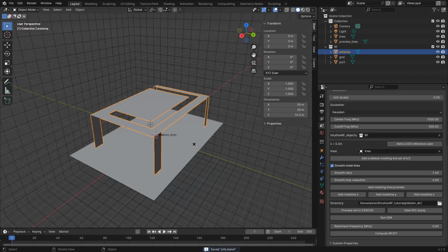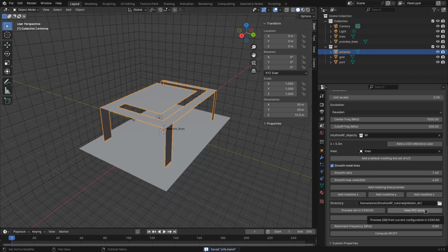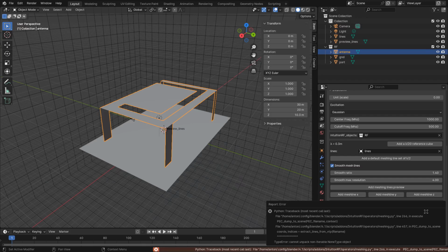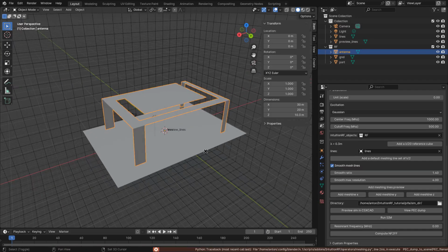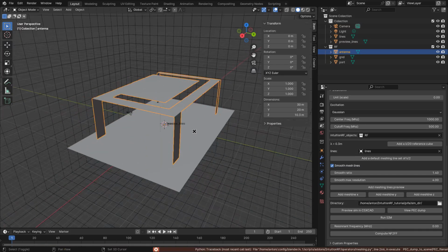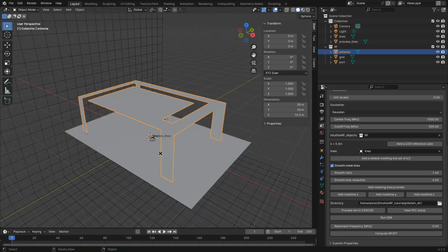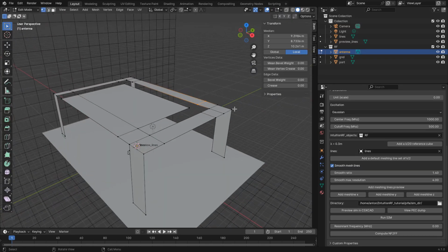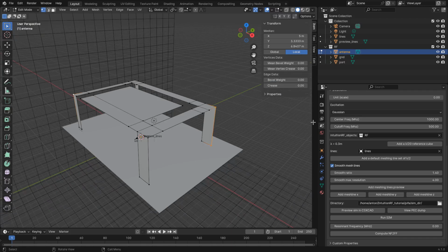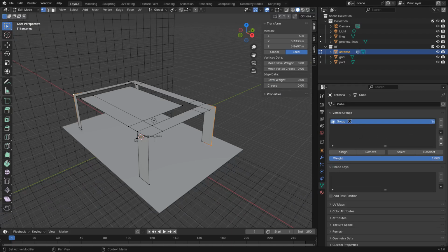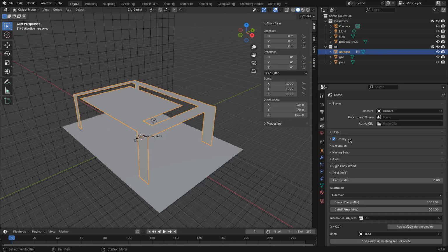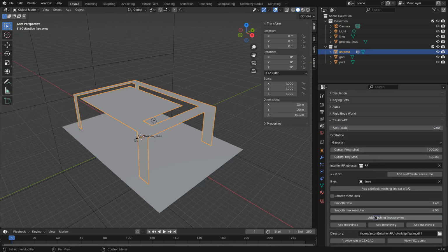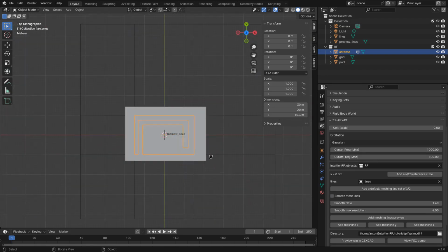Okay. So now we can preview the pack dump like we did before. Let's see. Okay, so it's unhappy. And the reason for that is that we didn't define any meshing lines that would match the metal planes. So let's do this. I will use the same method as before and add anchors. So let's select those 3 vertices like this. Assign, and now if we preview the meshing, that's correct.